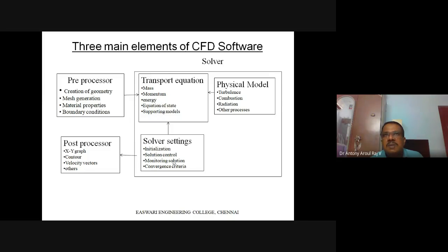Now I have gone there, and I am seeing all the residues are decreasing with respect to iteration. So that means good news. I understand that the problem is solving in the correct direction. I know that after some time I will be getting the solution. It is also possible that it may go in the opposite direction, so the residue may increase with respect to the number of iterations. You can know only if you are able to see the plot.